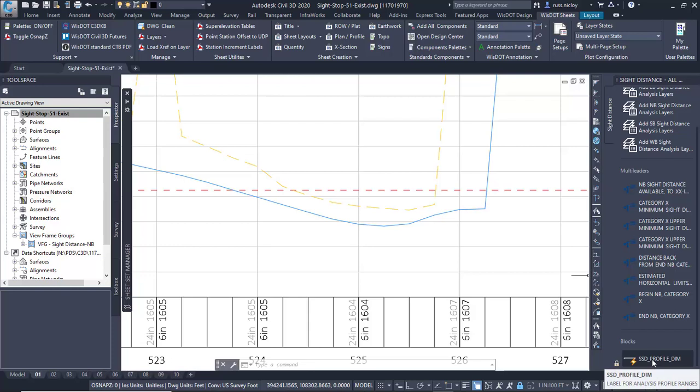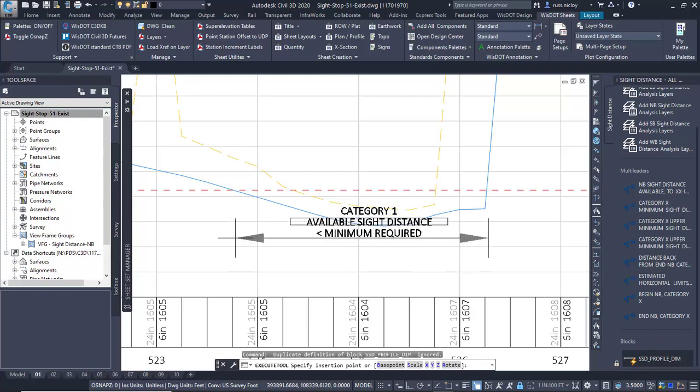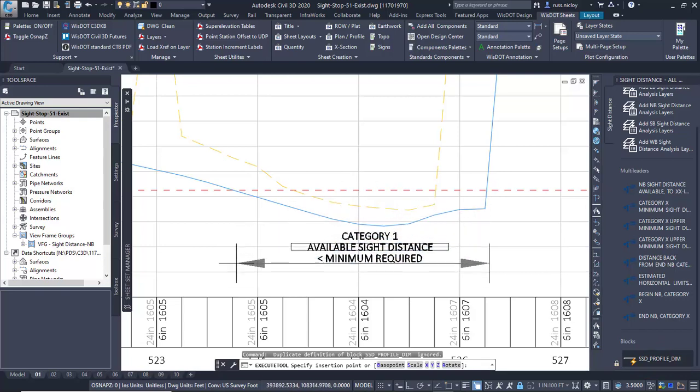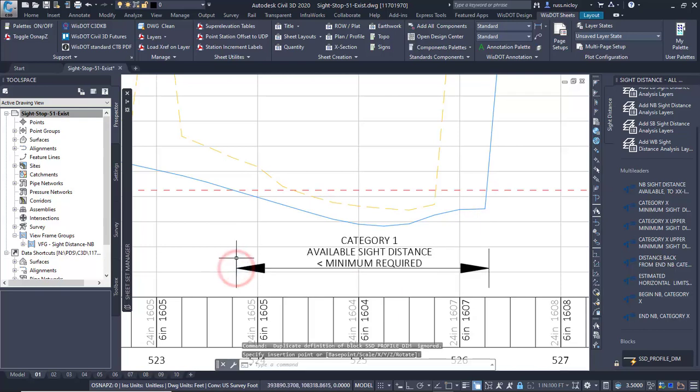It's a dynamic block, so we'll be able to pull it around and move it. I'm going to left click on that and drop this in. Now I'm going to eyeball where this is going to go, and literally just eyeball it. Left click a point right there. Now when I select this, there are a bunch of grip points that we can use.